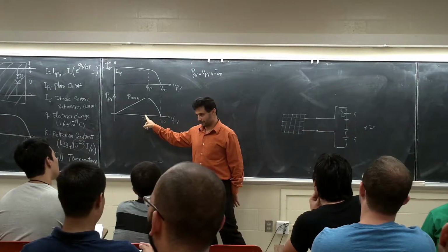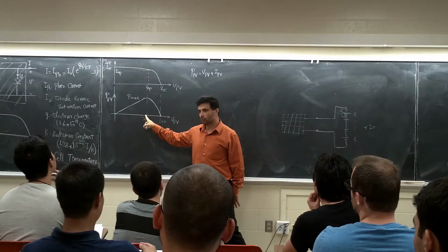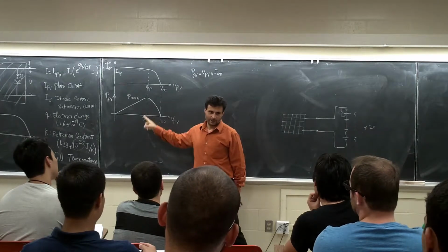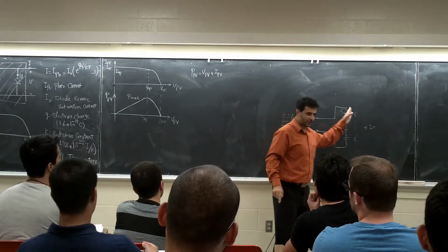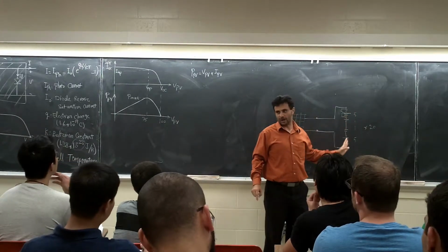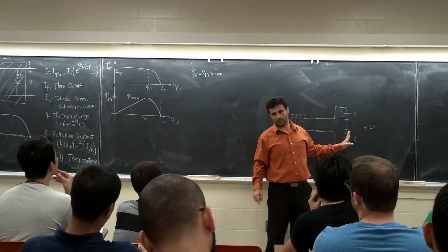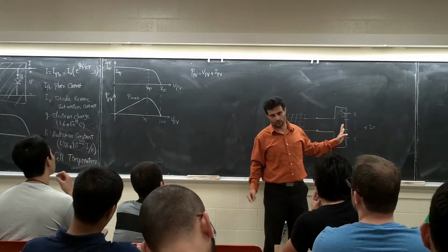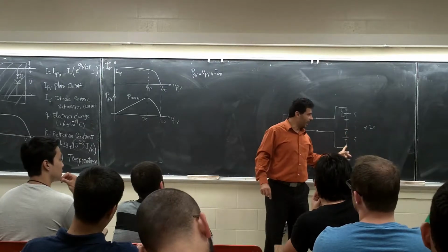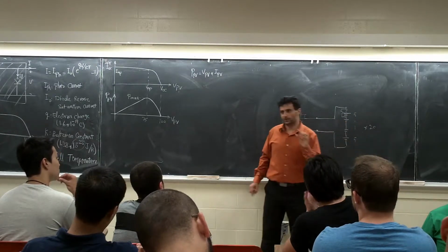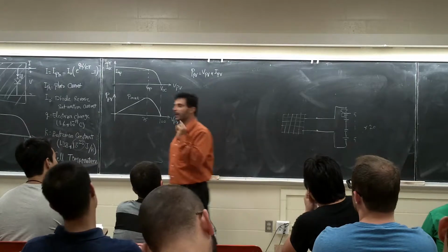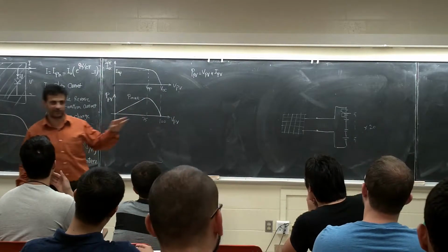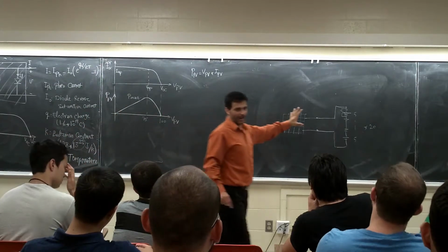So basically, you are setting that voltage. I am controlling this voltage. So I change my voltage here. I have a control algorithm. That's MPPT, maximum power point tracking. We'll talk about that. This control algorithm will tell me what voltage I should go for, right? In a real system, I don't have batteries like this. I have a converter.